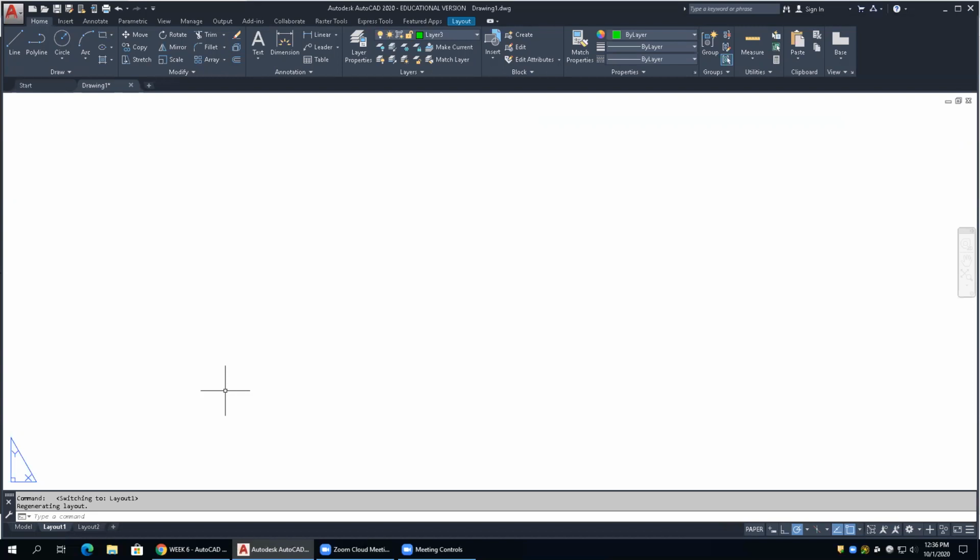What you're basically looking at is a sheet of paper. And this represents the sheet of paper that's going to be coming out of the printer. Okay? Now, what we have are 2 dimensions. This is the paper world, and it's 2-dimensional only. Okay? Notice the UCS icon over here. It doesn't look like our normal UCS icon. See that? That tells you when you're in the paper world. Any 3D command you would try to use, it would tell you that's not valid.